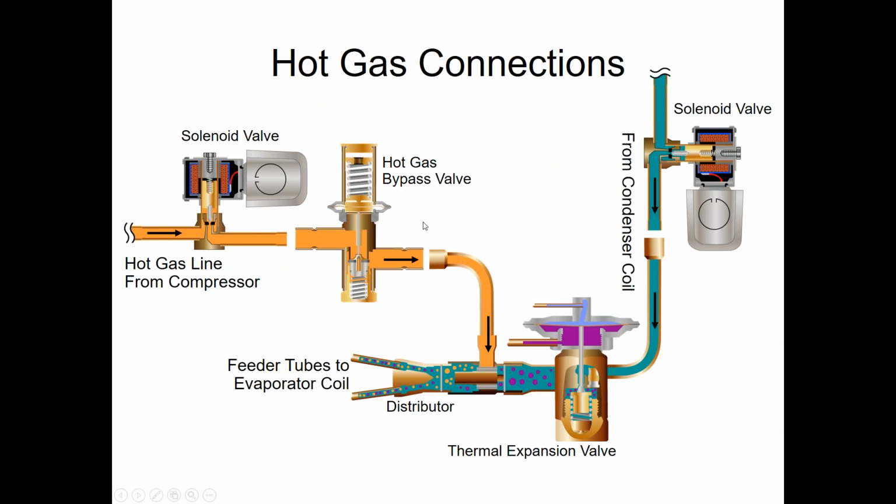well, back to this, if we looked at R22, we usually set these regulators to start allowing hot gas flow in at 57 pounds gauge suction. And on R410A, we're upwards of around 100 to 108 PSI gauge suction, where we start regulating hot gas in. So it's just a method of capacity control, and really at the end of the day, what it's doing is maintaining pressure and temperature in your evaporator, so we get proper oil entrainment, and we have proper pressures to keep us above freezing or frosting of the coil. So that's how this all works.